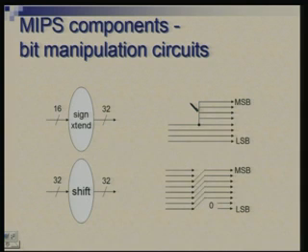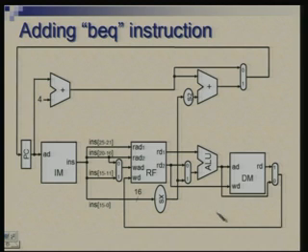Now just to remind you, we had seen that sign extension and shifting are essentially wiring. There is no active gate or any active component involved. Sign extension means repeating one particular bit, and shifting means just rearranging these and supplying a constant 0 to some of the bits. So in the previous diagram, the sign extension and the shift are essentially these kinds of wiring elements.